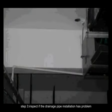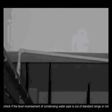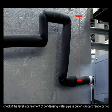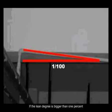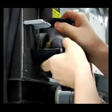Step 3. Inspect if the drainage pipe installation has a problem. Check if the level and slope of the condensing water pipe are out of the standard range. If the draining pipe is jammed, the condensing water cannot be discharged. Check if the lean degree is bigger than 1%, and if the pipe connector and throttle part are well heat insulated.